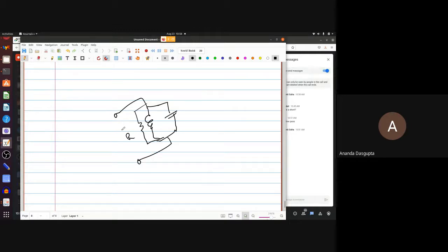Now you put everything like this and you have a VI. How much would VO be? Same as VI, exactly. Always, no matter what the frequency is, right? So it will not be a resonant circuit at all. That's a very nice question to ask, but putting R, C, and L all three in parallel would not give you a resonant circuit. In fact, the job of the resistance is actually very important.